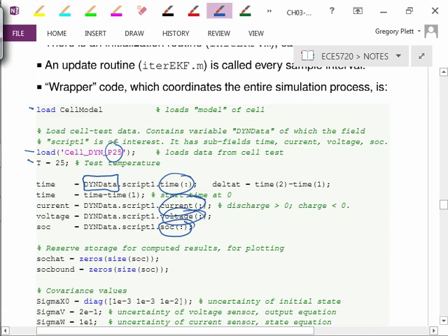This is something that in the lab test was calibrated, as we mentioned earlier in this chapter, by having a defined charge to 100%, and then I run my test script, whatever that is, to its end, and then I do a defined discharge down to 0% afterwards. So this point is calibrated, that point is calibrated, and I very carefully measure ampere hours in the middle, and that allows me to do Coulomb counting to get a state of charge estimate that, because it's highly calibrated, is a reasonable estimate of what the true state of charge is.